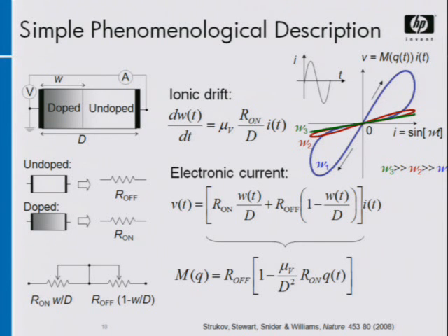And what you see is these two equations here are exactly the equations for a memristor. So this essentially showed that one way, anyway, of achieving memristance in a circuit is to have a system in which both atomic and electronic degrees of freedom are coupled and are time dependent under the application of an external voltage or a field. Once you have these two equations, it's easy to figure out what the memristance is. And so what you find out is that the memristance looks like this.